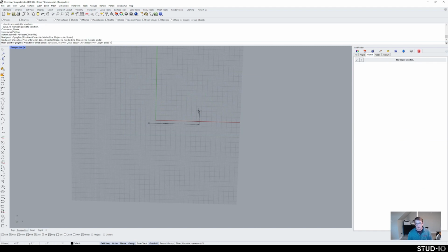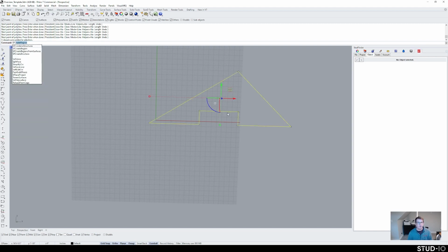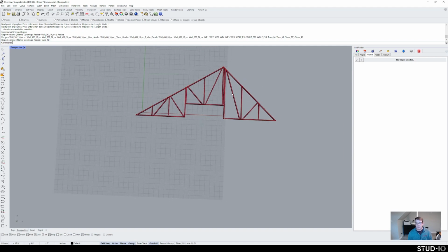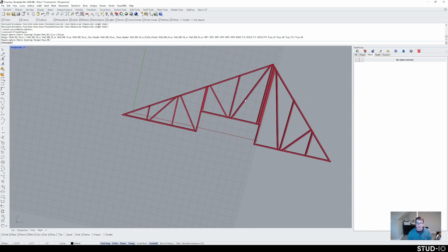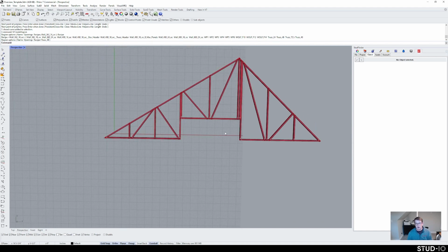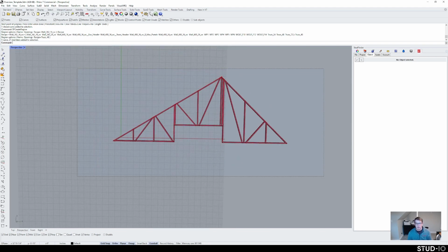So if you happen to make a crazy looking truss that looks like this, you can SF create region. Again, let's truss it at 48 inches on center. It will take that and subdivide it intelligently based on the rules, like this apex and these edges of this ceiling condition that's in there, and make those available for us. So a lot of things will be coming out with regions and trussing and all these common scenarios that you're going to get into soon. So keep an eye on that.